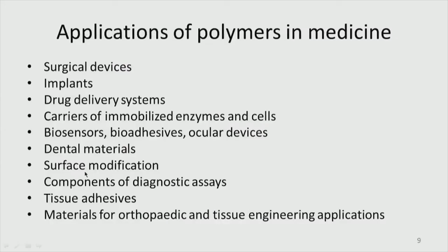So, all these are made up of polymers. Surface modification. Okay. So, we can modify metal surfaces by coating with polymers. We can have polymer inserts to avoid metal on metal rubbing. We can have inserts to prevent dissimilar bimetallic current being produced, and so on.